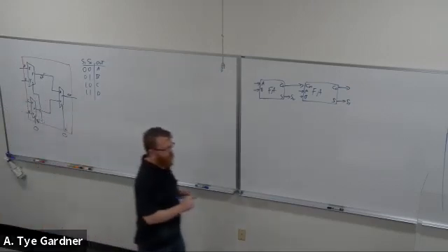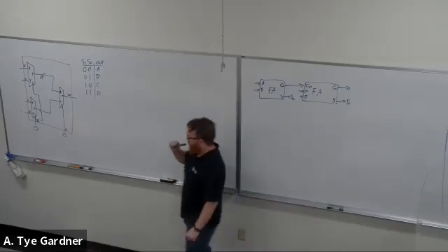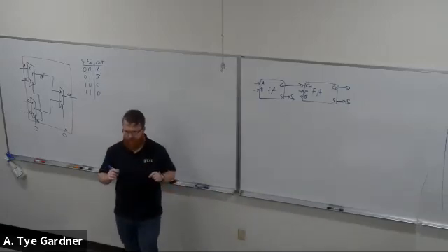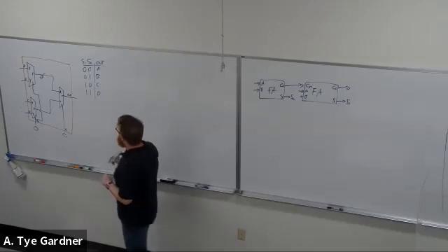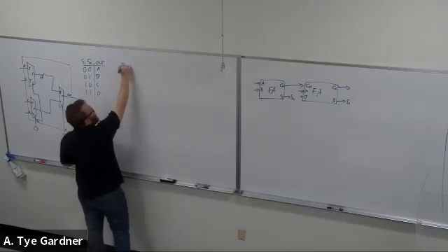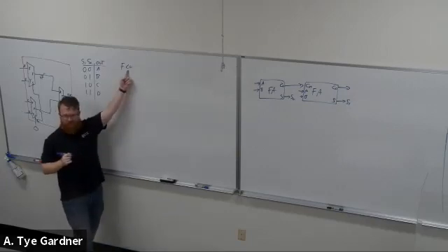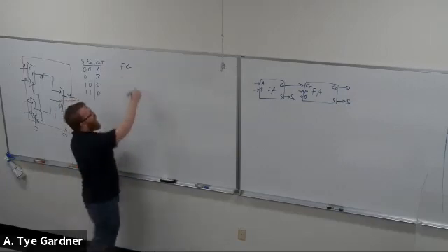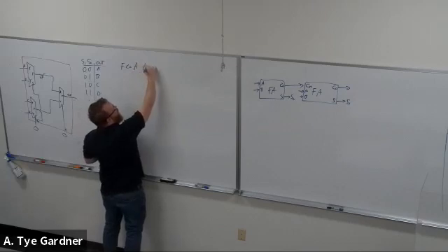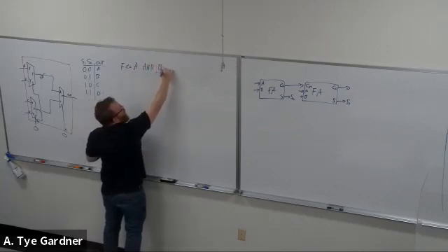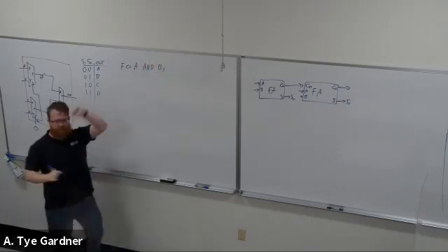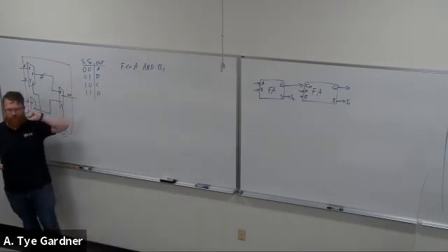Okay, so if I were to write an AND gate, this is one of the simplest ones. I'm going to use the term F. In VHDL, we use this kind of assignment statement. And I write A and B. This is not pseudocode. This is exactly how I would design an AND gate in VHDL.